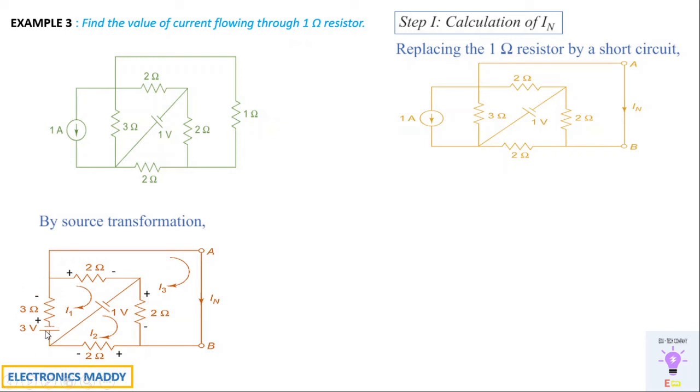So over here you have the voltage source. Be very careful, the current is in the downward direction, that is why the voltage source is also inverted, given as minus and plus in this way. I'll be indicating the direction: as the current enters, it will be plus, and when it leaves, minus. Write it with respect to each and every component, because then you will not go wrong.